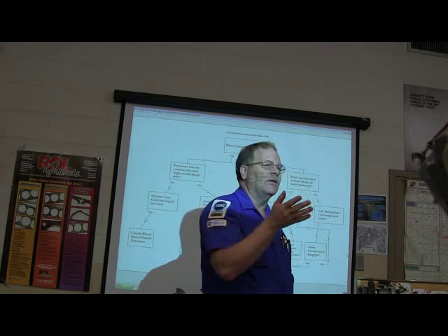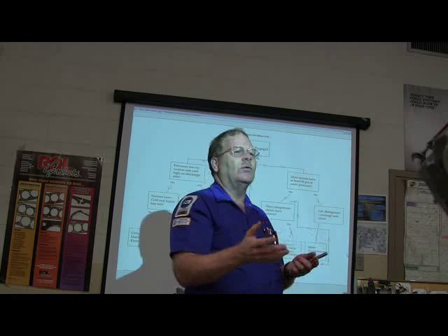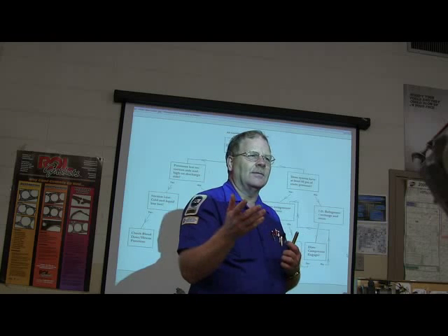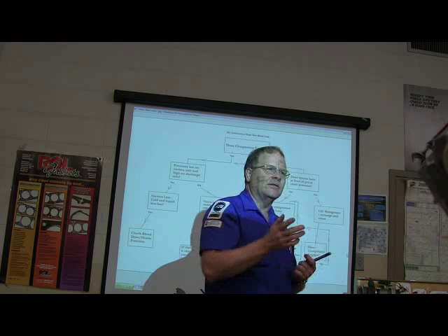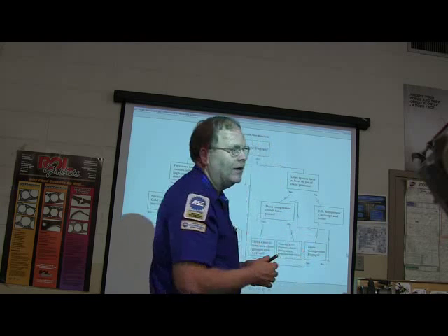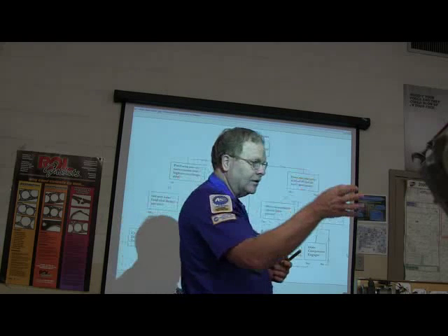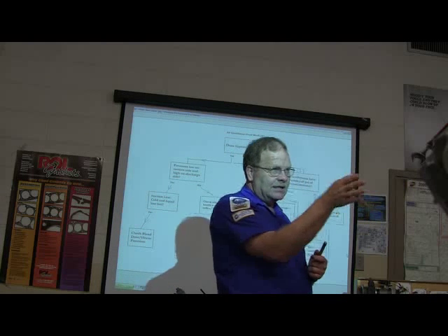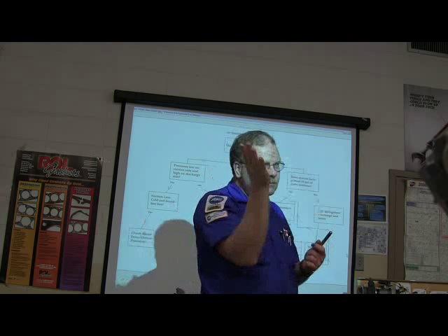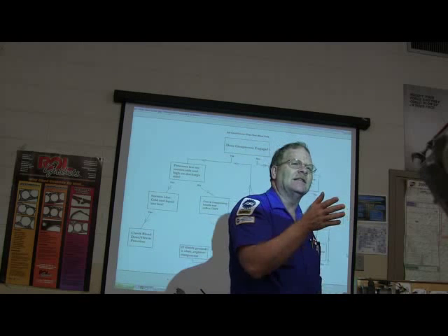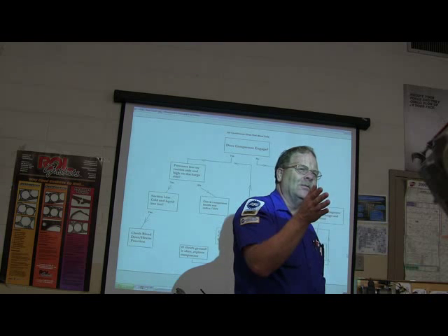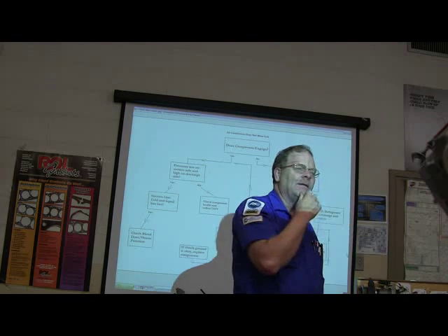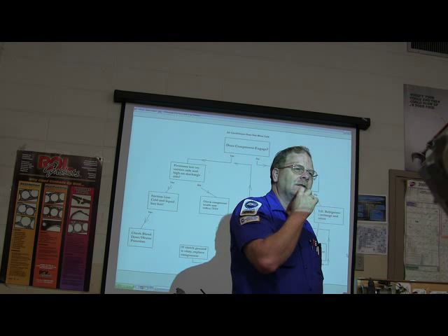All right. So we go to our scan tool. Do we have a request for compressor operation from the switch on the panel? You know what I mean? Is there a request? And what if the scan tool is telling you that the AC compressor relay is turned on, but the AC compressor is not running?